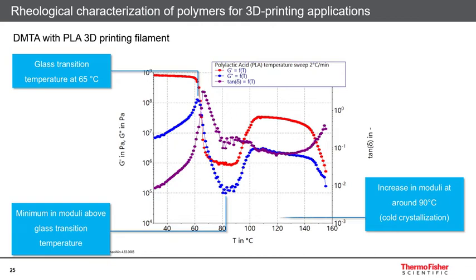Cold crystallization only occurs when the original specimen was processed in a way that included a rapid cool down from melt into the solid state. In those cases, the PLA chains do not have enough time to align and form crystalline domains before reaching the glass transition temperature. Below the glass transition temperature, the mobility of the molecules is reduced so much that no further crystallization will occur anymore, and the PLA shows a dominantly amorphous structure.